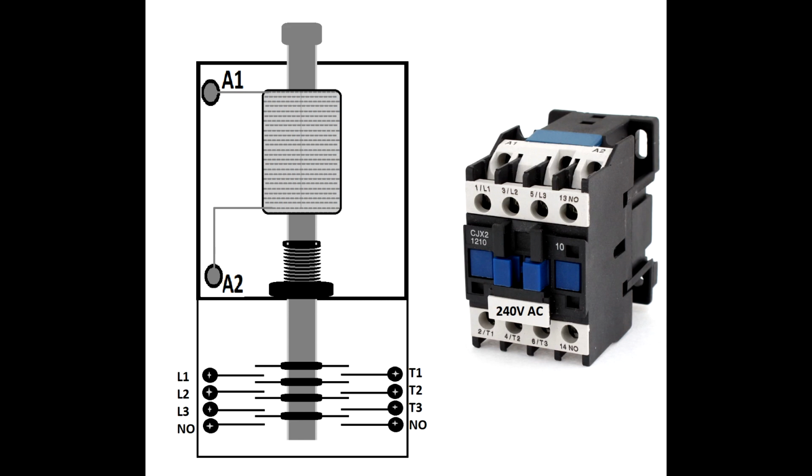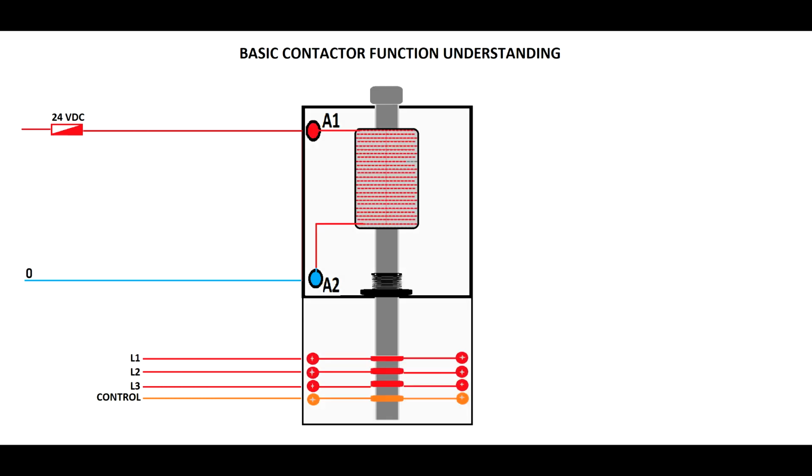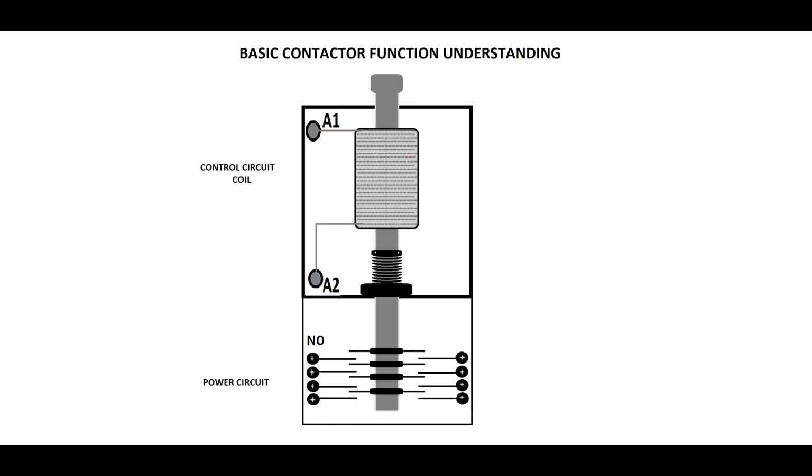This is the contactor. On the top you have the control circuit. To the bottom you have the power circuit. So you have a solenoid on the top, and on the bottom you have the power circuit. Now you see on the left hand side on the top you have a switch, and until you press that switch the contactor will not be enabled. Now I'll enable this contactor a couple of times to see what happens, and on the bottom you will see it will always allow this power circuit to pass by. You'll see also a little control. That's just an auxiliary switch which allows that control to continue its journey. I'll explain to you how this works.